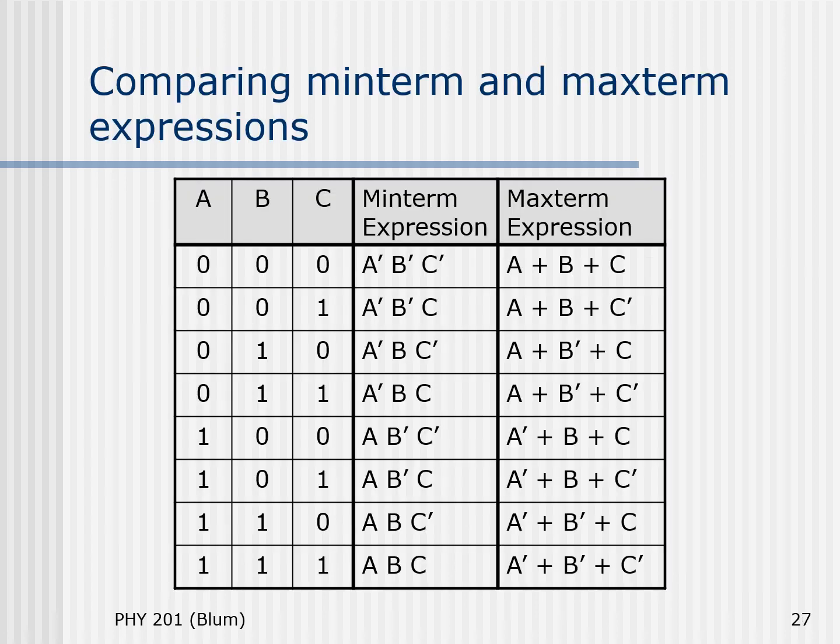So here we're just summarizing in one slide the expressions used by either approach. The minterm expression uses an AND, and the maxterm expression uses an OR. The minterm expression is trying to create a 1, and so if you see a 0, it's going to be primed.